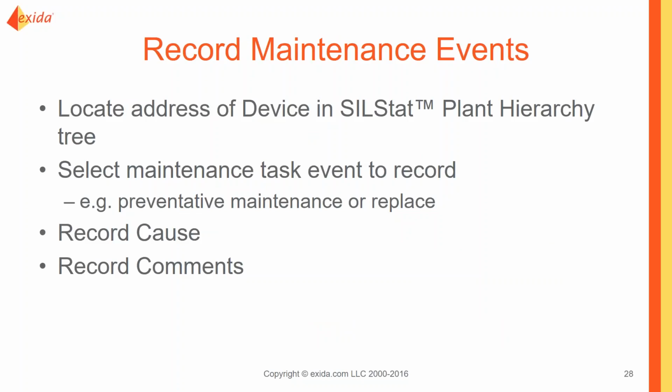Maintenance events are easy to record as well. So in this case, you simply locate the address of the device in the SILStat plant hierarchy. You select the maintenance task that you want to record. So some maintenance tasks are also predefined, and some aren't. So you can also input that as the user. You can record the cause of the maintenance if it's not routine, and you can record any comments to help with communication between the people working at your site.